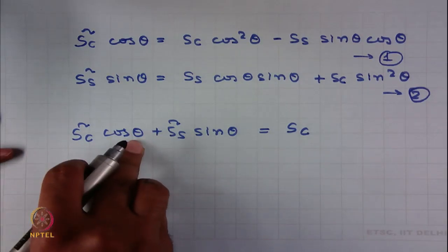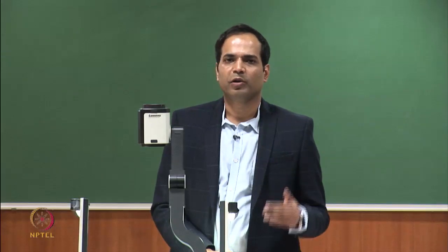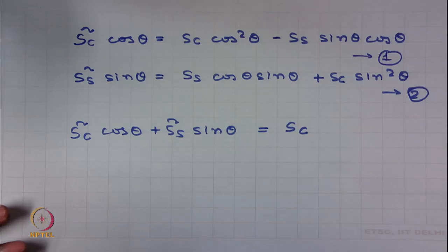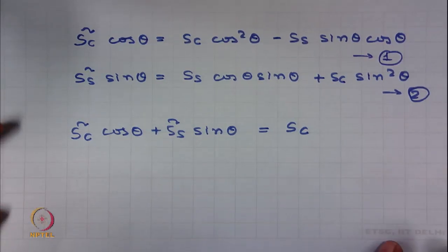you already know what the value of theta is. You have obtained this by doing some process of synchronization. The process of synchronization is simple. The receiver knows what is expected, the transmitter sends the same signal in the desired period, and based on the received signal it anticipates the distortion and can correct it. So, we know that after the phase of synchronization this value of theta has been obtained at the receiver.